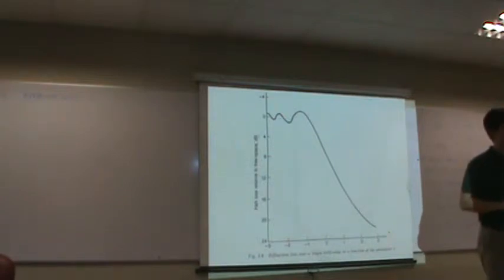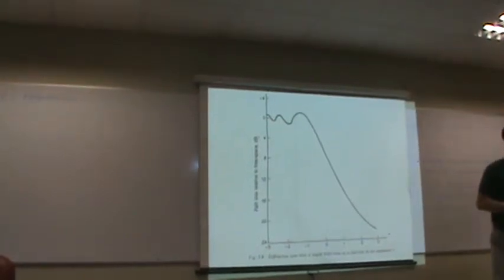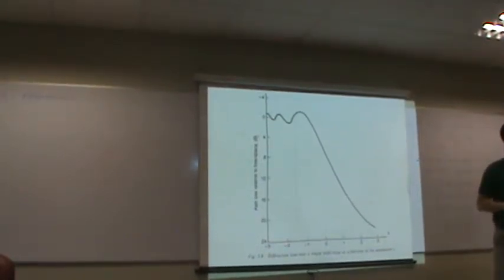We don't consider the width of the structure, because the knife edge model assumes that the obstacle is very thin and very sharp. So if the obstacle is wide, then we have to do something slightly different. Also, if the obstacle is round, I will discuss this later.